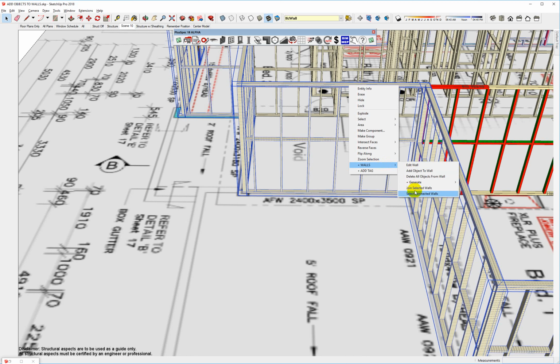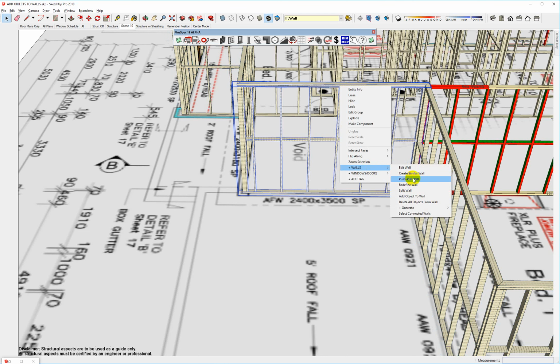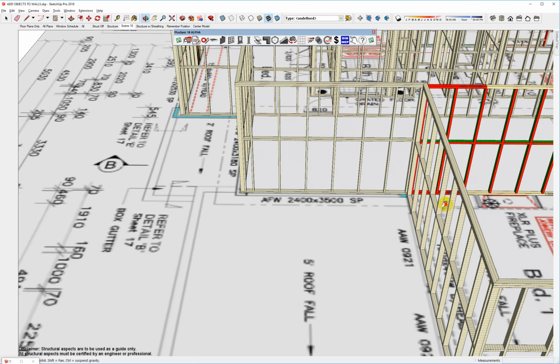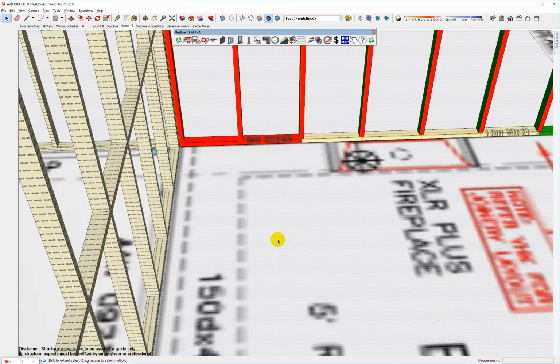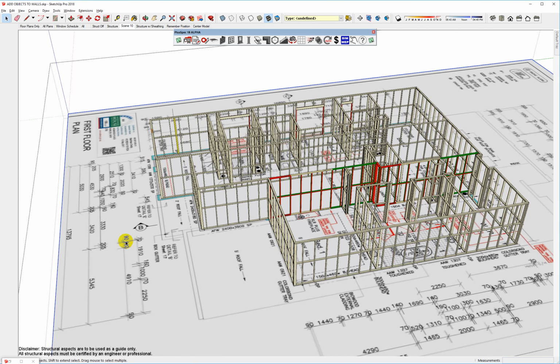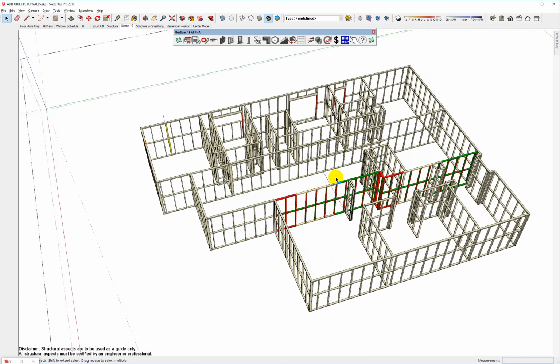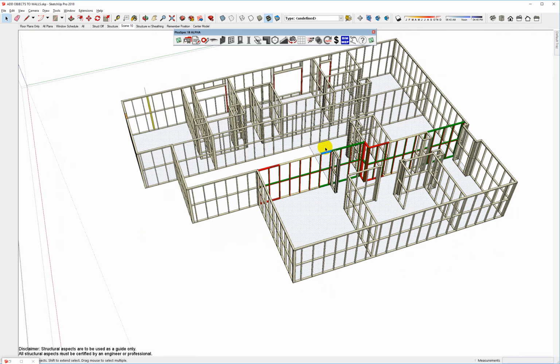Okay, in this particular instance, they're not actually joined. I can join the selector walls, and then I can create my walls from that. Walls, generate, face at base of walls. And now what you can see there, it's got a dotted hatch on it. Essentially, if I hide this plan, hide, you'll notice that I now have my face for there and my face